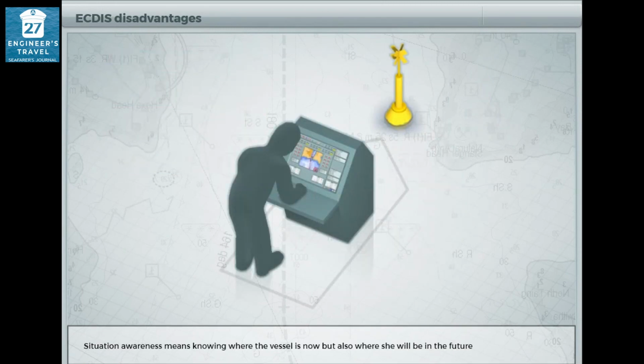The display size can affect the operator's situation awareness, particularly on a fast-moving vessel. When on passage at high speed, the small amount of chart displayed on the monitor means the operator may not be aware till it is too late of dangerously close objects ahead of the vessel.